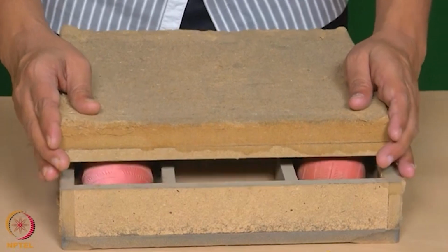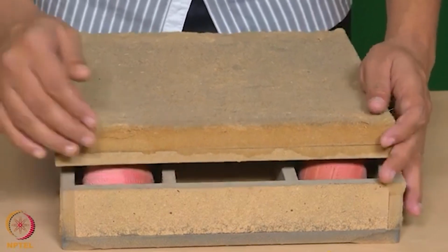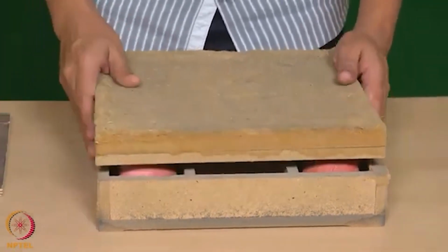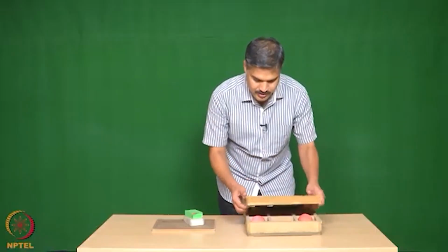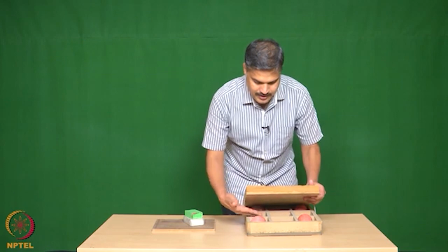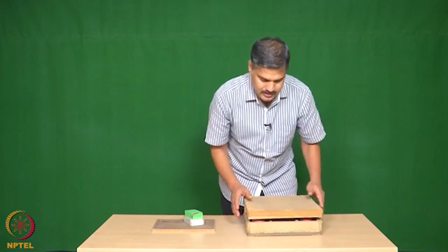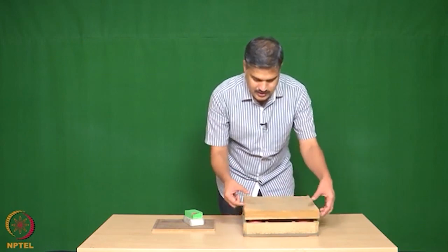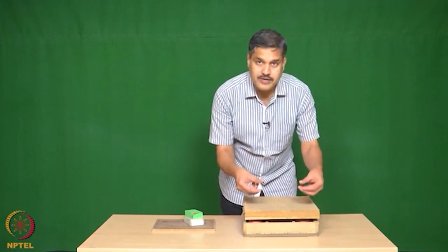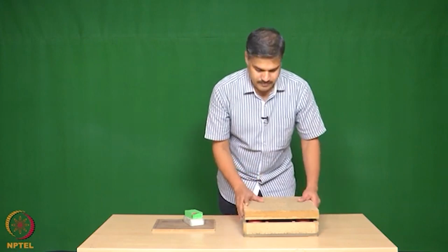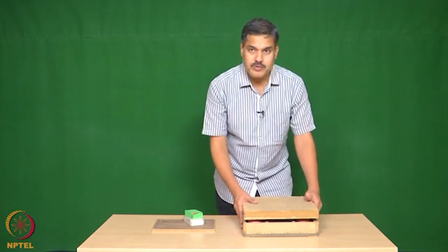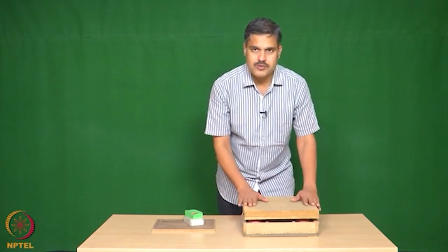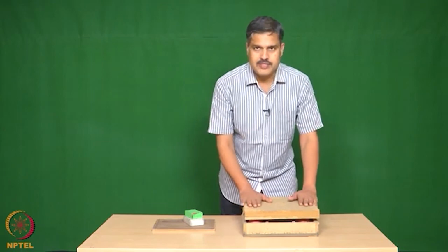If you look at this closely, it depends on how many; here in this case we have a full platform resting on these rubber bearings, but in some special cases these rubber bearings can be designed for individual columns. This base isolation is slowly becoming popular and it is used for short period buildings.